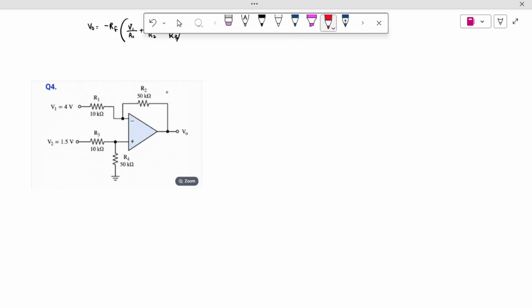First step, we're going to label our currents. There is no current going through these inputs. Second step, we're going to label the nodes here. So this node has some potential, and that node is also equal to this node because they're virtually shorted. Right, and then we're going to label the currents. So over here there is a current I1, there is a current I2. Now we know that I1 is equal to I2 because the current that goes in is I1, the current that goes out is I2, and this one is 0, so it's just I2. So I1 is equal to I2.